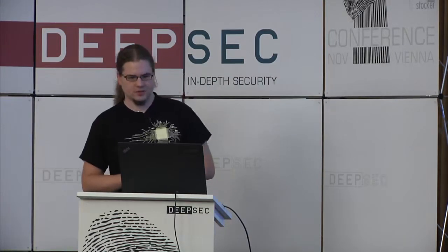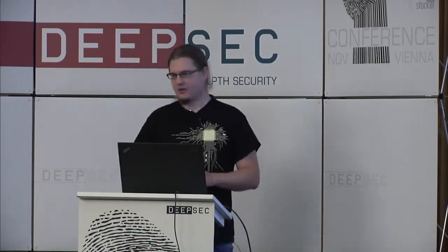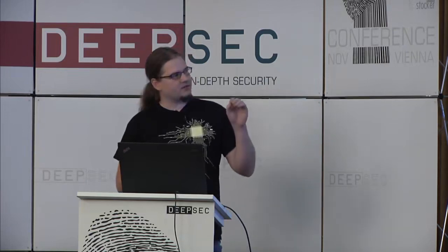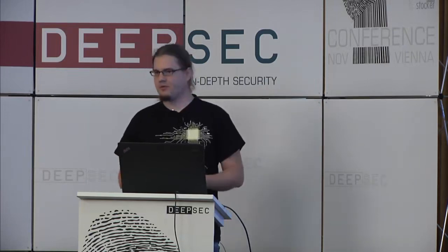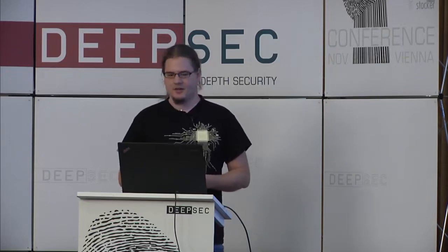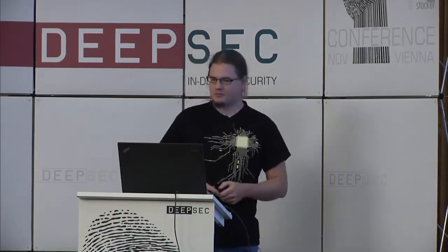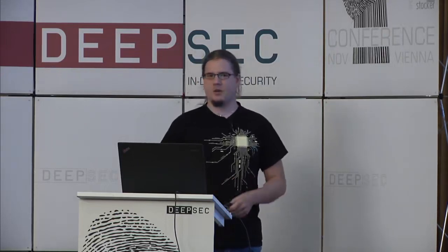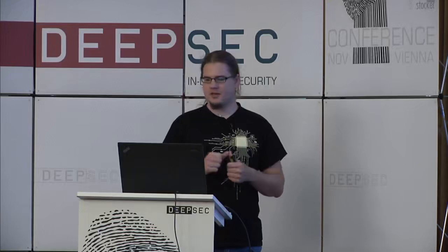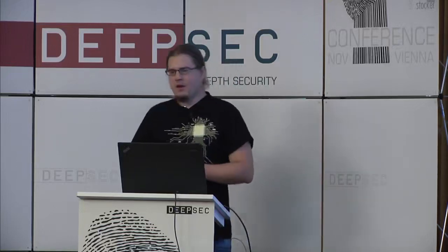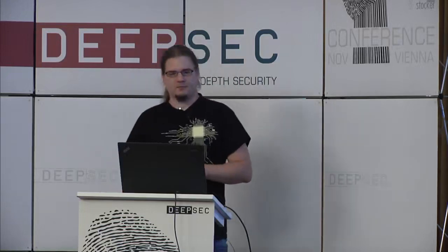This is where we have a closer look into the things we found, and the first thing we found was the obvious one. We had to extract the firmware in order to understand the device better. So what we tried is to hook up to the SPI interfaces that are available on these chips in mice, keyboards, dongles, wherever you want. And we tried to read them.